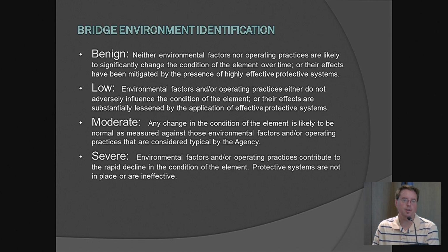If you have concrete girders, we'll use concrete girders. So if you have concrete girders and you have a lot of severe cracks that are showing a lot of dark stained efflorescence, and we know that the structure is sitting in a severe condition, we might want to look at those cracks a lot more closely, just to ensure that we're not having an impact on the rebar inside of the girders. So that's just kind of an indicator for the inspectors as to how to pay attention to doing their inspections and when to do them.